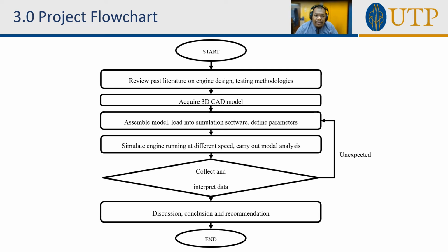Moving on, the project flowchart explains the flow of the project from its start to its end. In the beginning, we have the reviewing of past literature on the engine design and testing methodologies. After that, the 3D CAD model was acquired, and the model can be assembled and loaded into the simulation software, which is MSC Adams, where in the software we can define the parameters such as the bodies, the joints, and